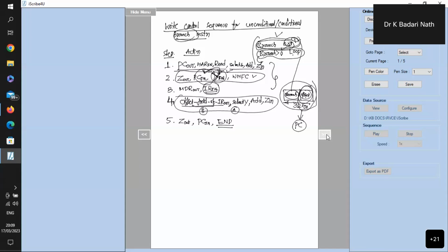So that means the whole of this instruction does what? It fetches the unconditional branch instruction into the instruction register, extracts the offset value, adds it to the new value of the program counter, that is PC plus 4, and loads it back into the program counter. So automatically you are getting ready to execute the program. The moment the program counter is loaded with the new value, it is branching, and you are ready to fetch the next instruction, which is at the new location.